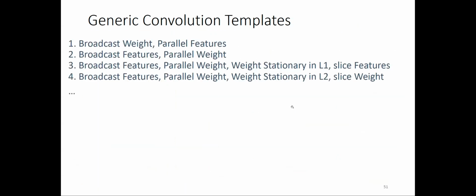And also we explore different kinds of these parallel strategies. So whether we do this parallelism on the feature map, or parallelize this on weight, or we parallelize the other data within the computation. So we identify the most commonly used data flows as templates, and then we generate these DSL for each template, so that we can compile the DMA operations for each template automatically.